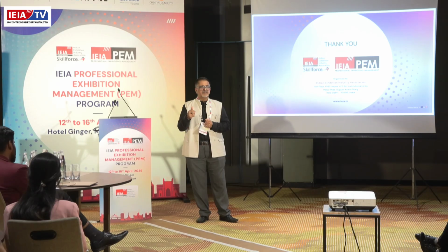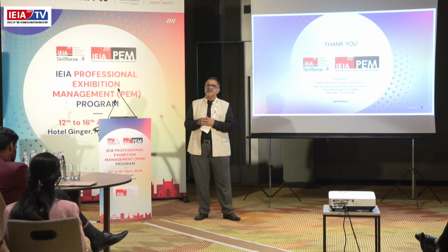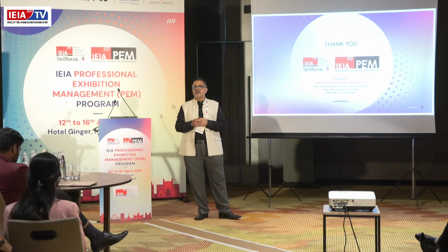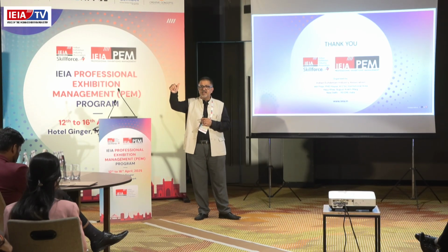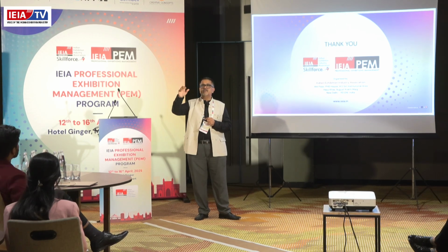See, fire is a state subject. Whatever rules apply in Bangalore may not work in Bombay or Punjab. So when you are doing an event, you have to check with the state fire rules on what they prefer. But as a thumb rule, a fire exit should not be more than 30 meters away from wherever you are.